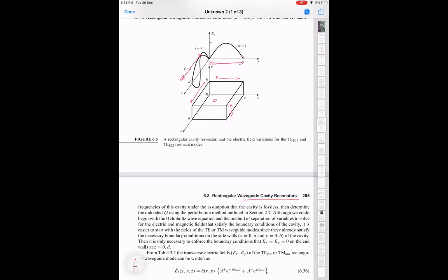So even these kind of resonances can be modeled with an effective LC model at the resonant frequency. You have some effective L and effective C. And this typical ratio of L and C will be different than the ones you achieve using transmission line. Because here these fields are propagating mostly in vacuum or air, whereas in your transmission lines, they were on a substrate, so there was some finite dielectric. So can you guess, how will the effective L and C change for a 3D waveguide cavity like this as compared to, say, a transmission line one? Will the capacitance be higher, lower, same?